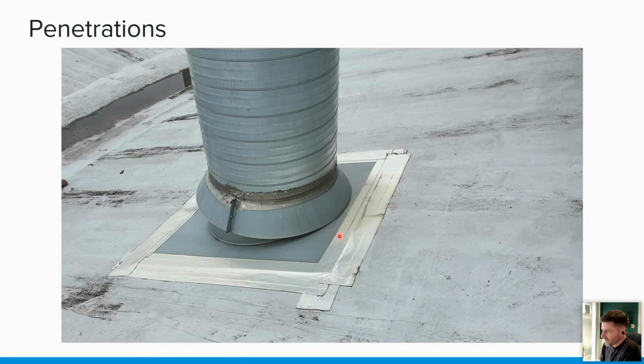And then obviously you've got this flange detail here, and again you've got that exposed detail there, so any waterproofing there. So what should have happened really is the waterproofing should be taken onto the flange and then finished underneath this collar detail here, where it would be well terminated and well protected, so that roof is likely to remain watertight.